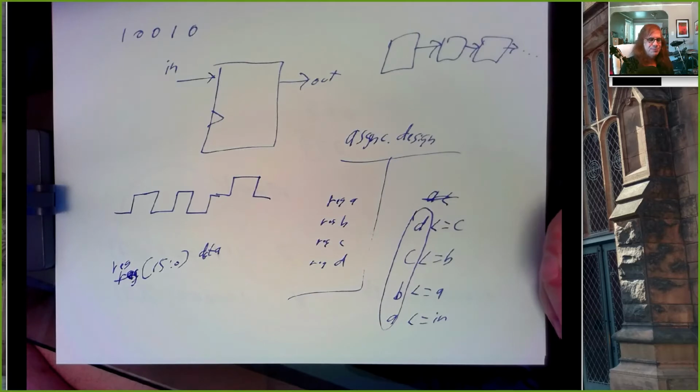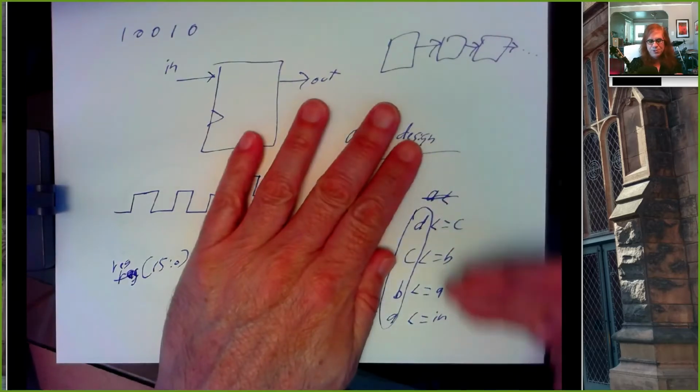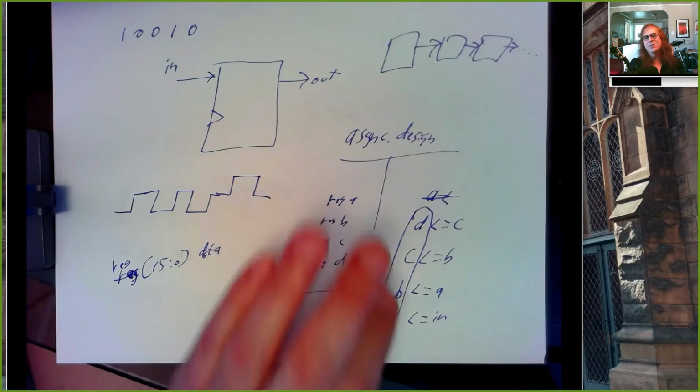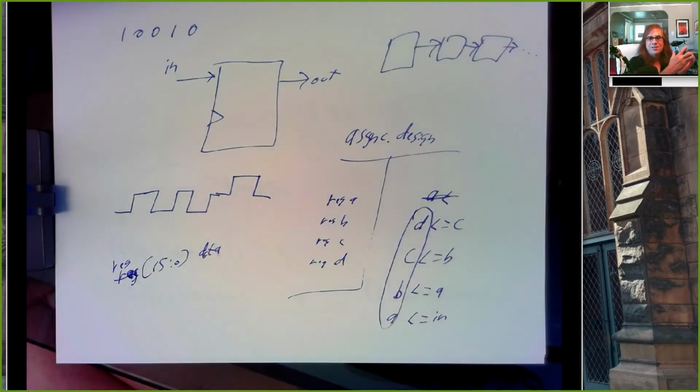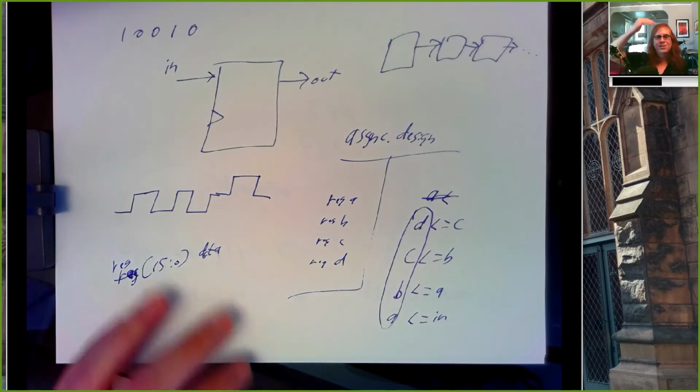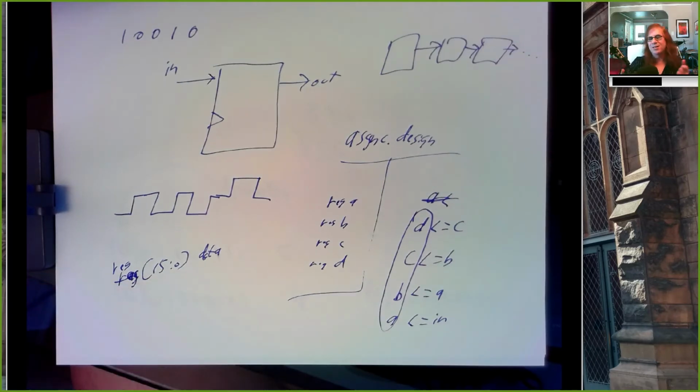But for loops get really strange really quickly in Verilog, because there's for loops that would let you do some statement 16 times, and there's for loops that actually synthesize hardware. And if you get those confused, you create a whole new set of problems and challenges to deal with. Don't be afraid of writing Verilog code that looks like you're repeating yourself 16 times or 20 times. There's nothing wrong with long Verilog.